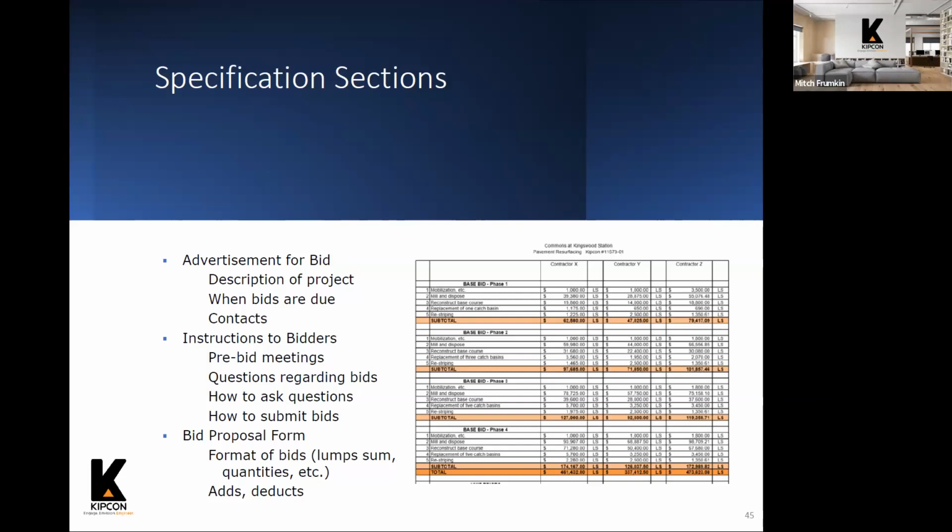They all have different formats for their pricing. So it becomes very difficult to see which contractor is the lowest bid, the highest bid, and how their extras in the contract might be structured that could affect the overall cost of the project. When you put together an organized set of specifications and a project manual and make that your bid package, it's much easier to compare the information you're receiving back.